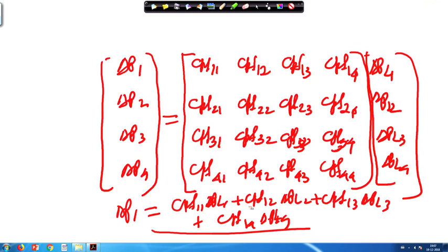Delta PL1, PL2, PL3 and PL4 are the power demanded by the 4 different distribution companies, and CPF is the contract participation factor, which will be specified. So, you will know the contracted power demands delta P1, delta P2, delta P3, delta P4. Generally we write delta Pi as the contracted power; sometimes we write delta PCi, where C stands for contracted power. It is the same thing.